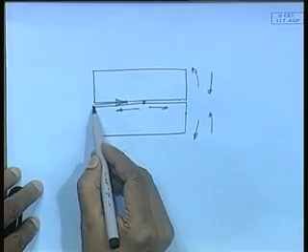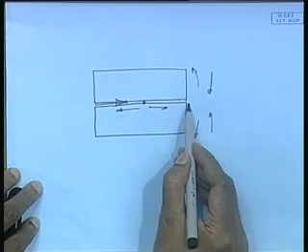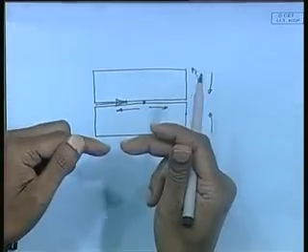That means the sequencing of welding is done such that the effect of one welding nullifies the effect of the other welding. That means instead of starting the welding from one part and going to the end, or starting both from the ends and coming to the center, we start from the center and go towards the ends, because here three sequences are possible.